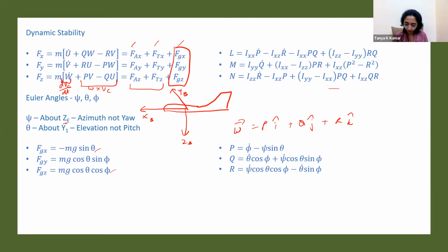And when you are subject to an oncoming velocity V, we take the stability axis to aid in simplifying the equations such that your x dash is oriented with this. You have a perpendicular to it, perpendicular this way. If your y body was something like this, your y dash is like this. So this is your stability axis. The x dash and y dash are the stability axis.